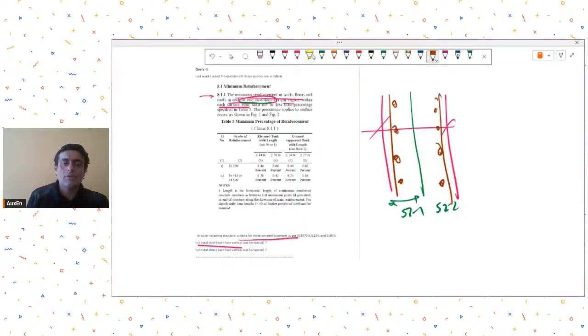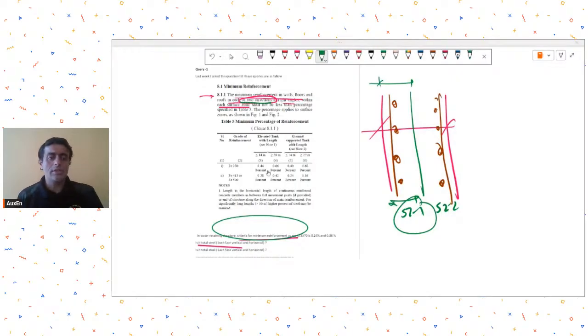Now the surface zone width has to be calculated. There is a figure given after this table. You have not taken that in the screenshot. So there is a figure given which tells you how to calculate the surface zone thickness, and on the basis of surface zone thickness from the reinforcement percentage, then you can find out the AST required and then you can provide it. Number one.